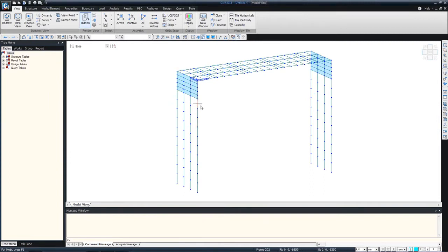So how was this modeled in AutoCAD? I'll just explain to you. So all these beam elements which comprise the composite steel girders, they should be modeled as lines. So nothing should be polyline in AutoCAD. And then you have the piles, again, they should be lines with all the required intersection points already made in AutoCAD.